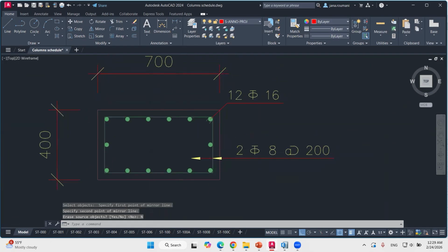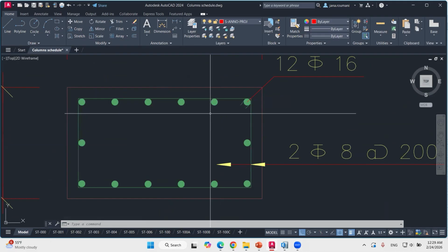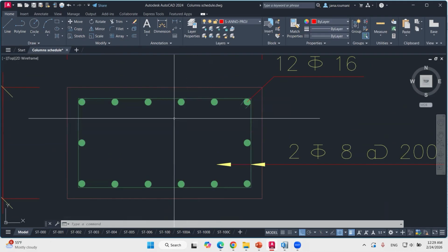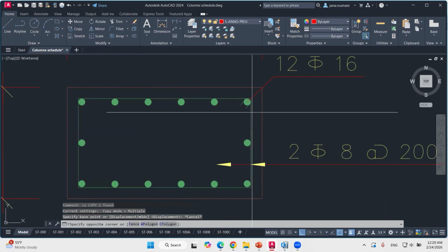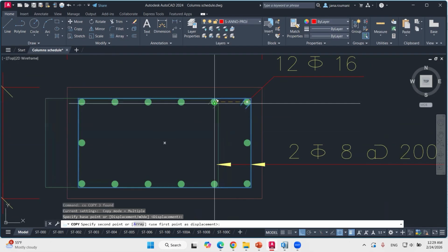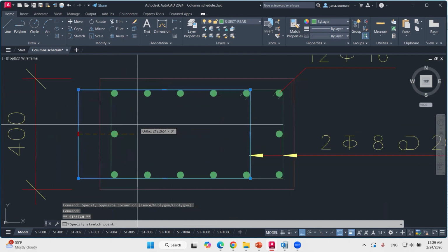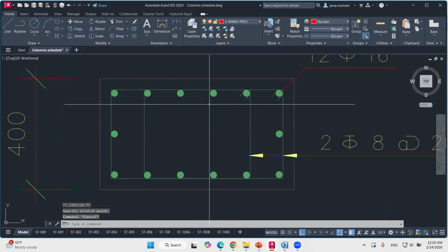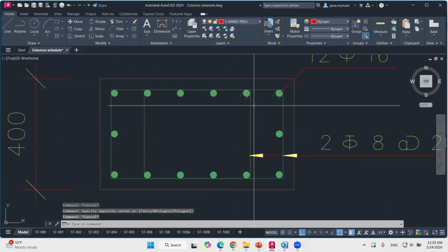This is the bars. Now for the stirrups, as we said, we cannot leave all of these without stirrups. So the perfect thing to do here, okay, if we consider what we did previously, we cannot do the same here because if we did this here, and considering the symmetry, we have 2 rows of stirrups that are not within a tie.